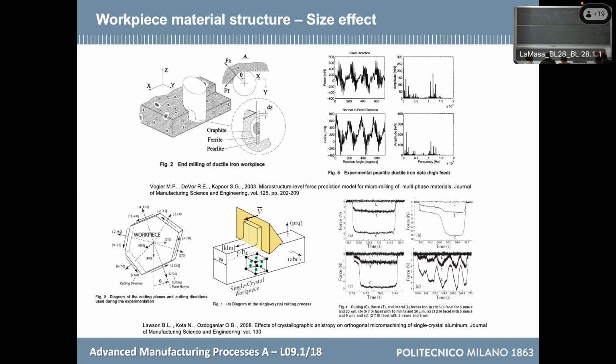the force, because on average, you have an average distance between one type of grain and the other. And so when the mill is passing through, it feels a different resistance of the material. And this could be bad because the mill is suffering vibrations. At that scale, you could have even bad problems of fatigue, and so you risk breaking the mill for these reasons.